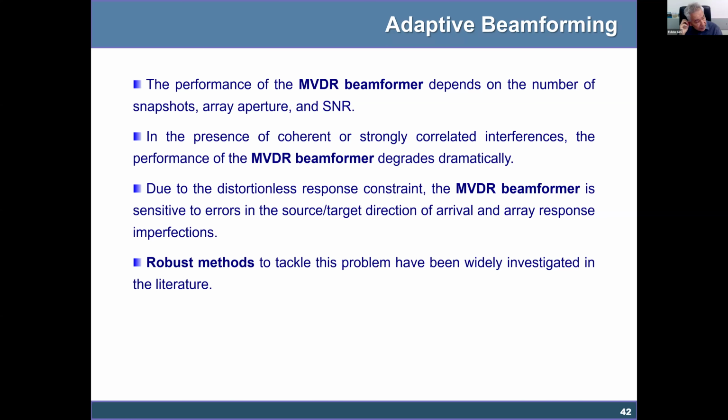So you may have sources that are correlated, but because it does not make use of this information, it is very robust to the presence of correlation between sources. Unfortunately, in the Capon beamformer, in the expression of the beamformer you have the inverse of the data covariance matrix.